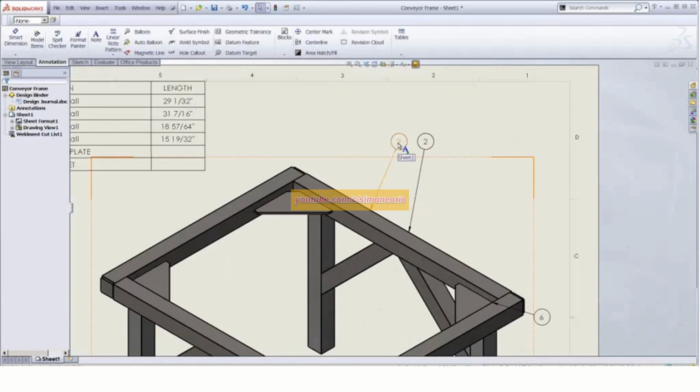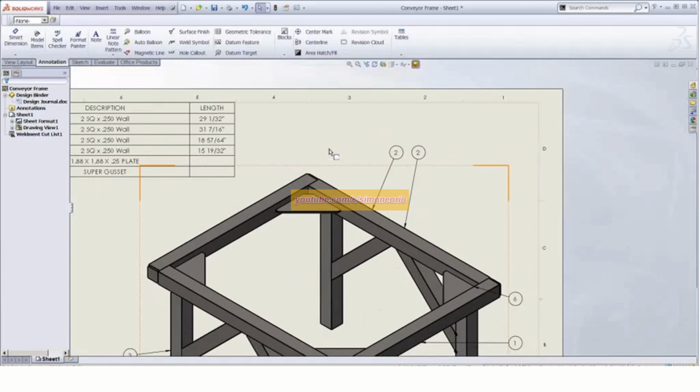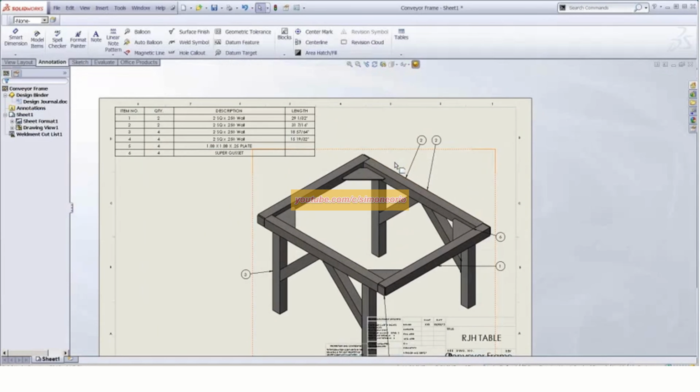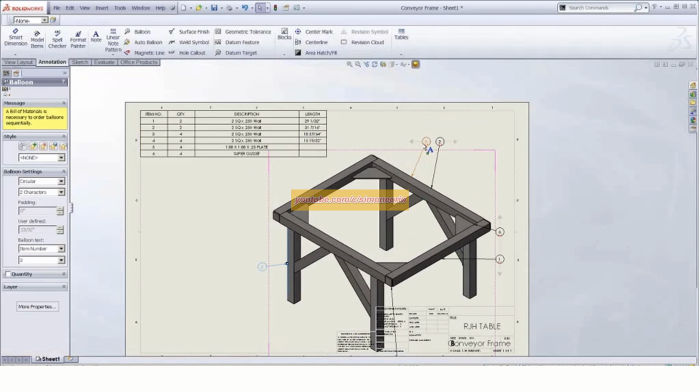Stock numbering is just an item number to match. This is something that always got me. In my case, when I did bill of materials, the top half would be the item number, and the bottom half would be what page that item was actually detailed on. So before, in my template file, and again, this could be a quantity in here, what we could do with this, let me go ahead and get rid of these.